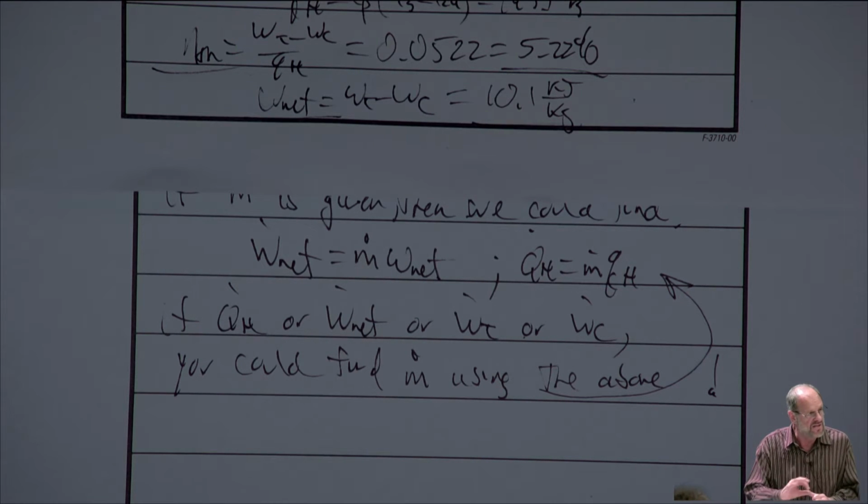But that's okay, because one of the things I also mentioned at this point was that compressed liquids have approximately the same properties as a saturated liquid at the same temperature, right? And that would apply to enthalpy or internal energy or entropy or specific volume, any of the properties we'd be dealing with on a daily basis. For compressed liquids, we just take saturated liquid data at that temperature, and that's just fine.